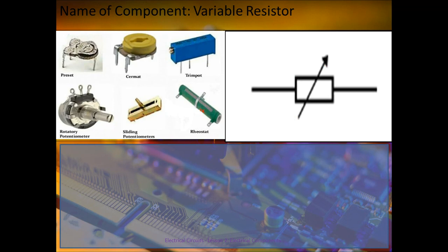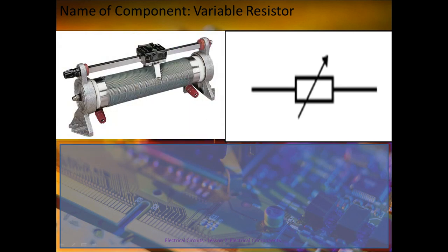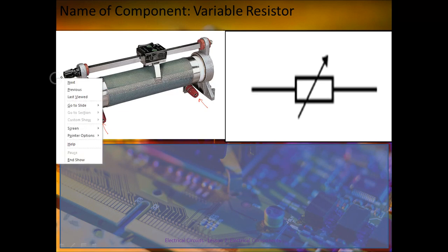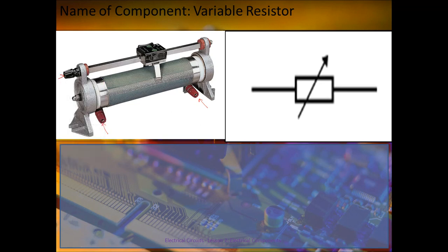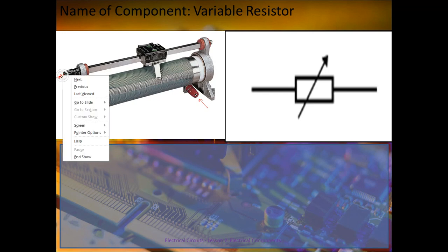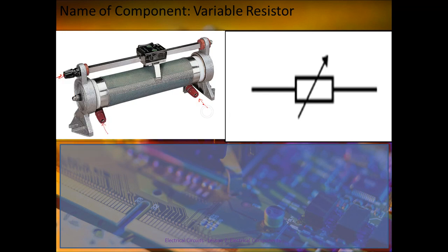And you can see there's several different types for this. The one we're going to focus on is that one bottom right, the rheostat, because they're the ones that, should we ever return to school, that you'll be using. Now, the design of these is that they've got 3 inputs, 2 on the bottom and 1 at the top. And the design that we'd be interested in, because we don't want it to act as a rheostat, we want it as a variable resistor, we would have a connection at the top and then a connection at the bottom on the opposite side.